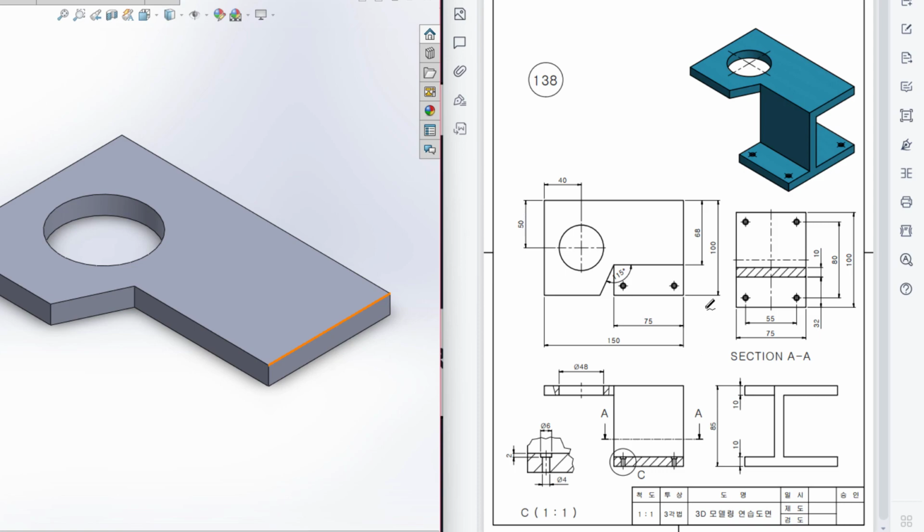So after that we can see we have another shape like here, rectangular shape, and this rectangular shape, if we draw it from the top view, we can see we need to draw a rectangular shape like this one, and this rectangular shape has a horizontal dimension of 75 unit, and this vertical dimension here is the 10 unit. Then I will extrude boss it to 85 minus 10 minus 10, so it will be 65 unit.